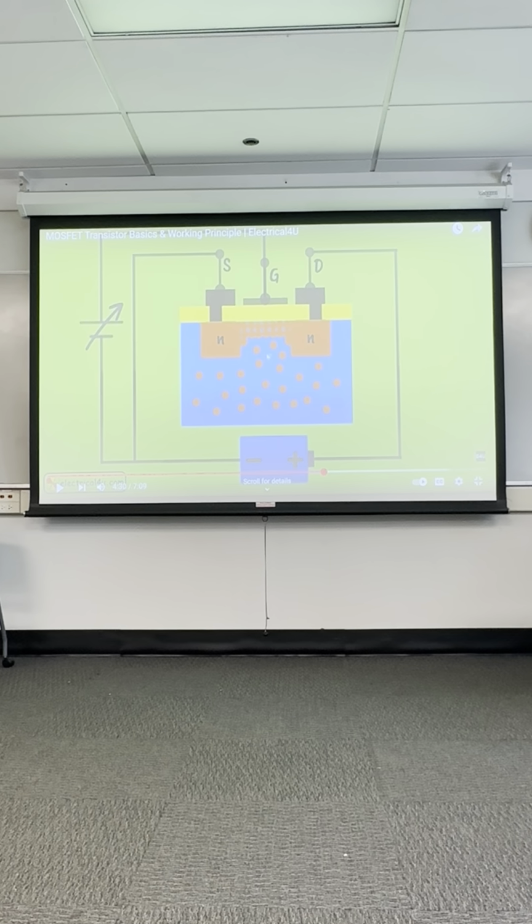They start forming an electronic bridge between the drain and the source. And once this voltage gets high enough, there's a path for current to flow between the drain and the source. This battery here is called the gate to source voltage.